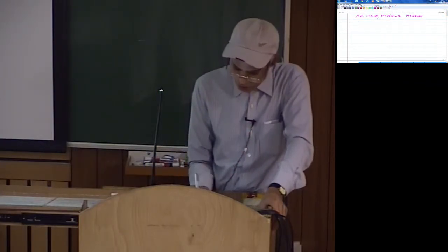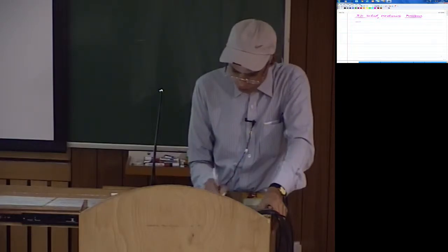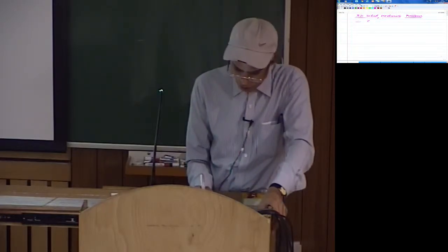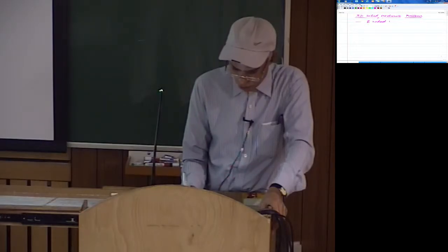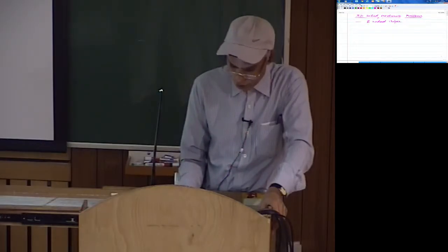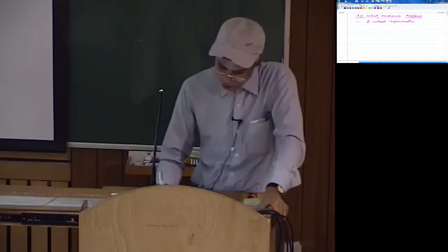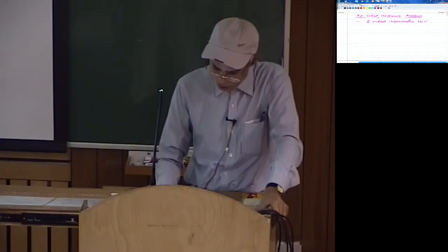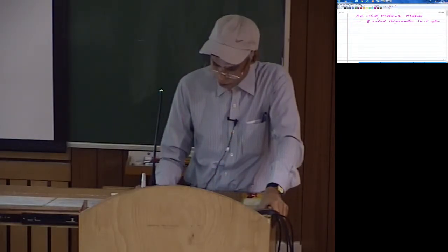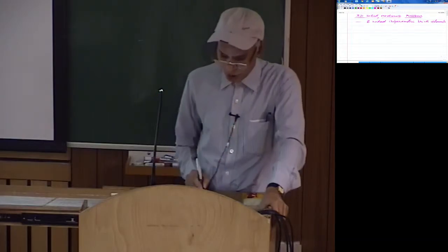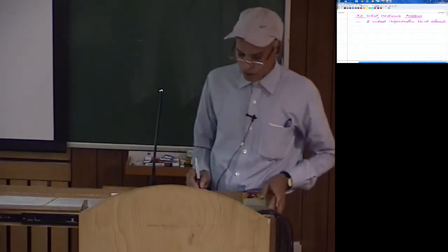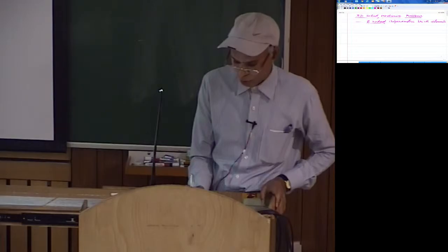So what we are talking of, the specific case, let us say, is the 8 noded isoparametric. Typically it's a parallelopiped, so typically it is referred to as brick element. So let me use the same terminology. So the 8 noded isoparametric brick element, that is the first example I am going to take.